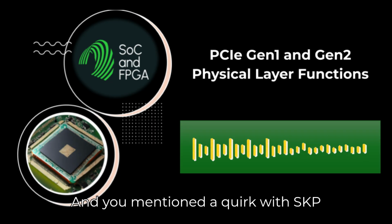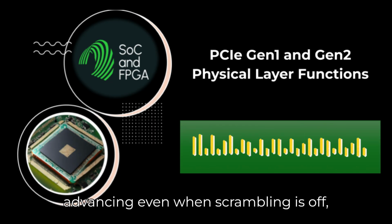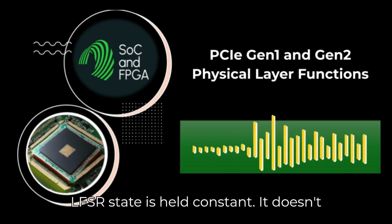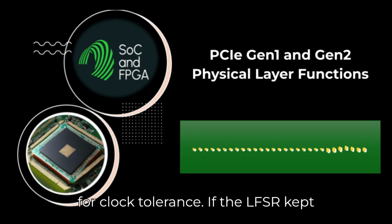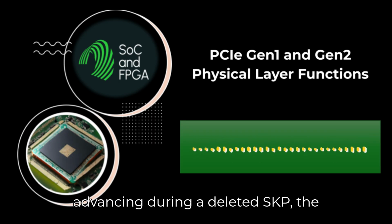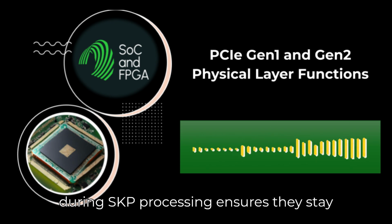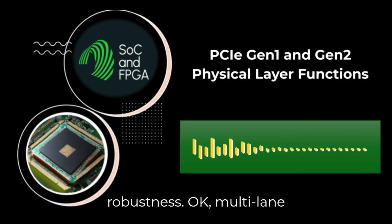Makes sense. And you mentioned a quirk with SKP symbols. Right. Normally, the LFSR keeps advancing even when scrambling is off, but when an SKP symbol is being processed, transmitted or received, the LFSR state is held constant. It doesn't advance. Why that exception? Because the receiver might add or delete SKP symbols for clock tolerance. If the LFSR kept advancing during a deleted SKP, the receiver's LFSR would get out of sync with the transmitter's. Holding it steady during SKP processing ensures they stay aligned even if the SKP count changes slightly. Another subtle detail for robustness.